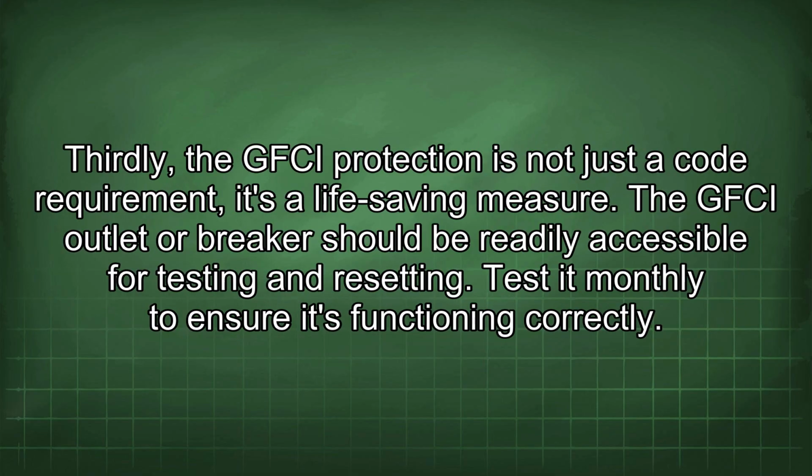Thirdly, the GFCI protection is not just a code requirement, it's a life-saving measure. The GFCI outlet or breaker should be readily accessible for testing and resetting. Test it monthly to ensure it's functioning correctly.